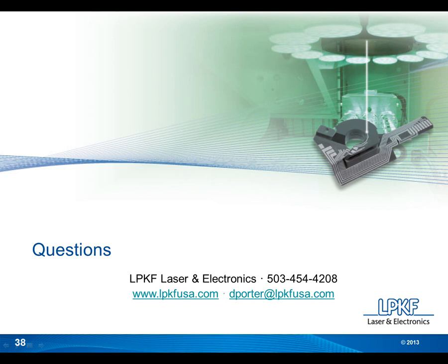Looks like we have a question from Nicholas, who asks, are there sources for data, for example, adhesion strength between plating and plastic between different LDS grade plastics? I think I understand what you're asking for, and yes, when we qualify a plastic, we measure peel strength and plateability basically on the part, and we do have characteristics for all the approved plastics available.